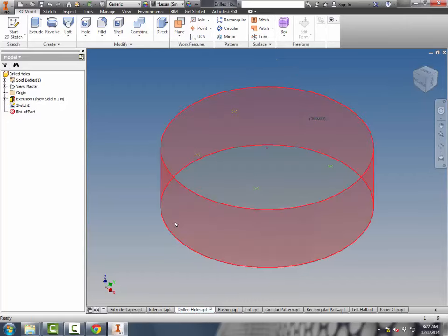This is probably the trickiest one of them. We're going to use the different hole features to build 5 different types of holes. If you're looking at the instruction sheet, all the sizes and specs for those holes are on there. The key thing is that if I want to place a hole, I have to select which point I'm placing the hole on. Otherwise, it's going to put the same hole on all 5 of these points.